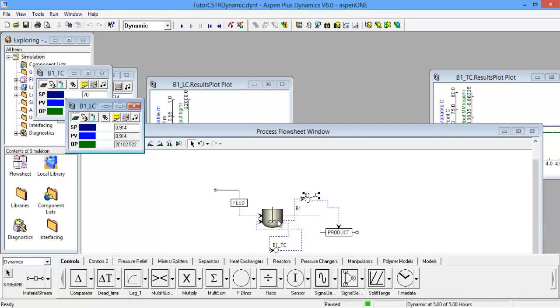Okay, this is the plant, which is the reactor. The signal being sent out is the process variable, which is the level. It is going to send the signal into this controller, and the controller will compare it with the set point. If there is no difference, then it's going to open this flow loop with this amount of flow rates. Okay, I hope we get that.